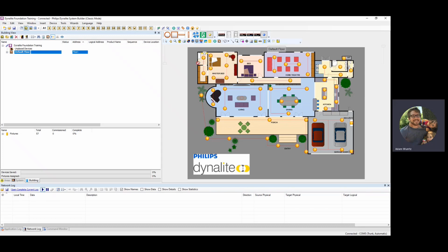There's a number of ways to do this. You notice when I hover over this, I get a 1. So if I select that, go to the next one, and click, it makes 2. It links them together. Now it's ready for me to do a third, but I don't have a third in this circuit. So I can right click to end it, or if I want to keep going, I could go 1, 2, 3, and then double click the last one. Now I still have the tool selected, but I've broken the link so I can start a new circuit.